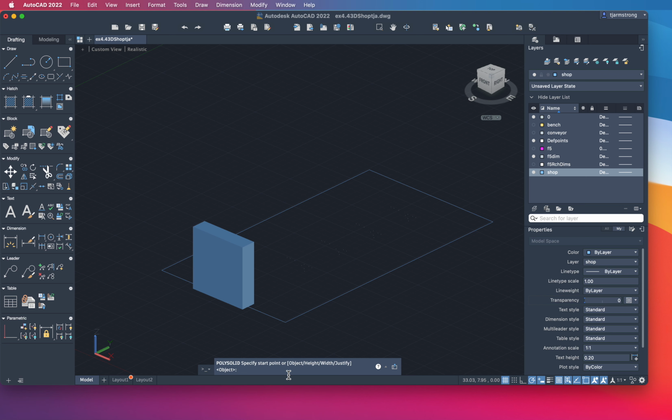But you can see one of the options here is height. And we want our walls to be 6 meters high, so I'll just check to see what is set for height. It says 6 meters. Okay, that's fine, so we'll just leave it where it is. And I'll type return, and we'll check the width. We want that to be 0.25 meters. So I'll type width first, W-I-D-T-H. And it's default set for 0.25, so I'll leave that where it is. If it weren't, I'd just type 0.25.